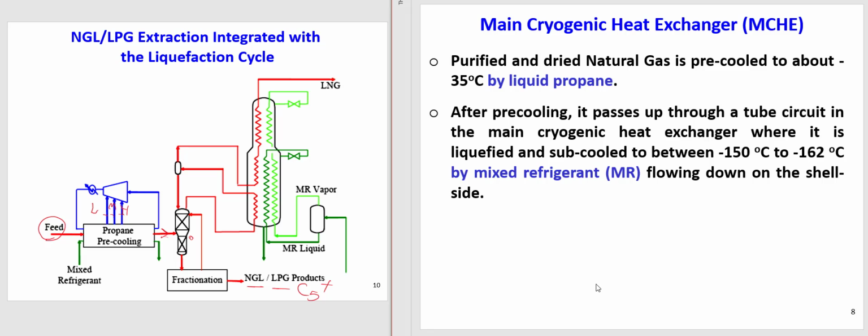So after that, this is not what you see in this photo. Here it is talking about just one step of pre-cooling. Let's say after the low pressure evaporator, it reaches 35, then a lower temperature in the medium pressure evaporator, and at the end, in the high pressure evaporator, it reaches minus 25. Then it exits and goes to the scrubber.